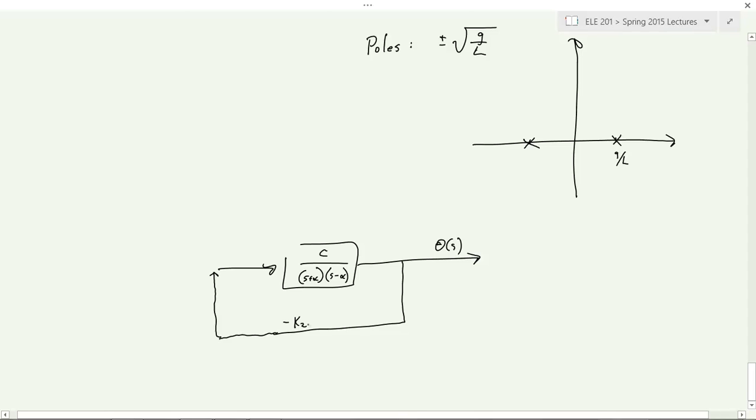So it's actually not stable. They're right on the imaginary axis, so they're not stable, but they're almost stable. So that's why it sort of stands up. But what would you expect to happen to a system that has poles on the imaginary axis? If it has poles on the imaginary axis, you would expect it to just be an oscillator. It would be like a sine wave. And maybe it would start oscillating bigger and bigger, which is kind of what this is doing.